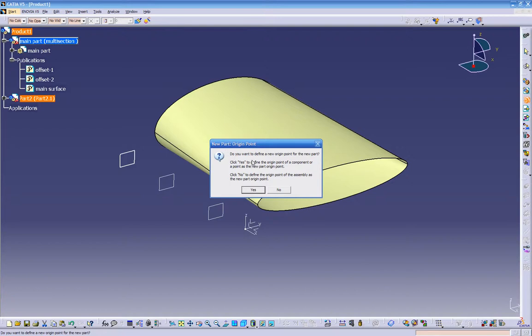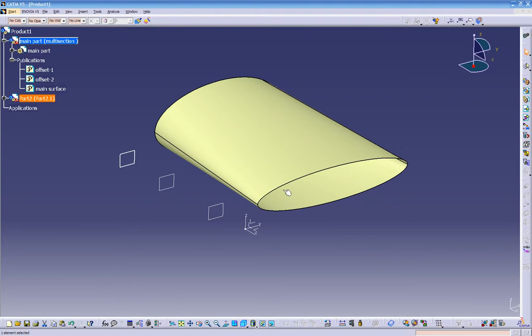When you start putting a whole bunch of parts together, we always want to make sure that we use the main axis for the airplane. Every time we insert parts and pull parts out of the assembly, we have to make sure that we use one axis, because if we keep creating new axes, we're gonna mess up the assembly. So in order to make sure we do this right, I always just say no. So I'll just click no.